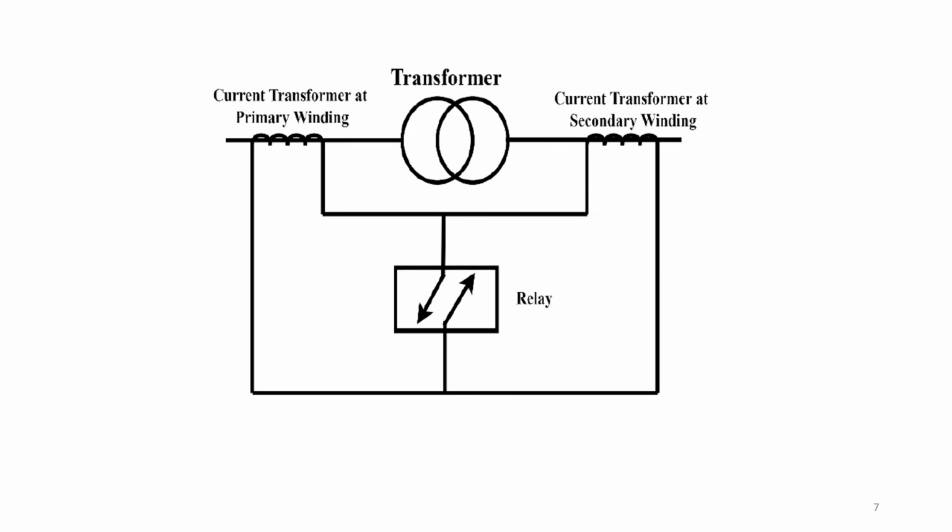The MATLAB Simulink platform was used to investigate the power transformer differential protection relay, and the main idea is to safeguard the power transformer from internal defects and keep it from being disturbed by external factors. The relay trip time was created according to an external source, which will create a discrete signal to trip the breaker. The collected results show that the proposed differential relay is a suitable course of action. Inrush, fault and no-fault states might all be distinguished by the suggested relay.